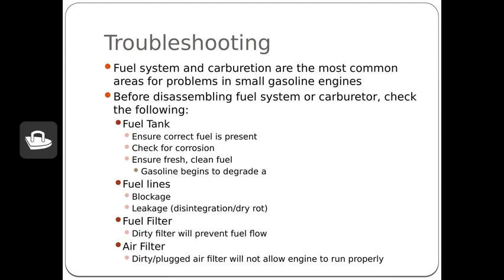It's mostly because it's a lot more convenient for where I live to go to a gas station that has an ethanol blend versus driving several miles out of my way to find a station without ethanol. The problem tends to come when ethanol sits in tanks. Ethanol, as an alcohol, is a very good solvent, and what solvent means is that it's good at dissolving things. And that is an unfortunate situation when we're in a small engine world, when the things it's dissolving tend to be rubber gaskets or some of the seals in our engine, and then we get this gunky, sticky residue that can start to build over time.